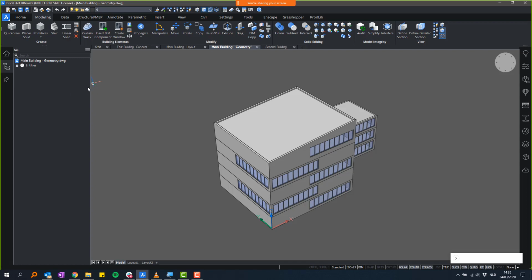So the structure browser, I didn't mention this before, but it's a very useful tool as well. It basically shows you everything that's in your drawing structured in a certain way. So for instance, in 2D, you could use this to sort on layers or filter on a certain entity type. Here in BIM, you can use it to sort on classification type, IFC classification, to sort on building and story, for instance. And you will see if I go to my classifications that currently in my drawing I have 64 solids and 14 block references. But there is no more information than that in my drawing.